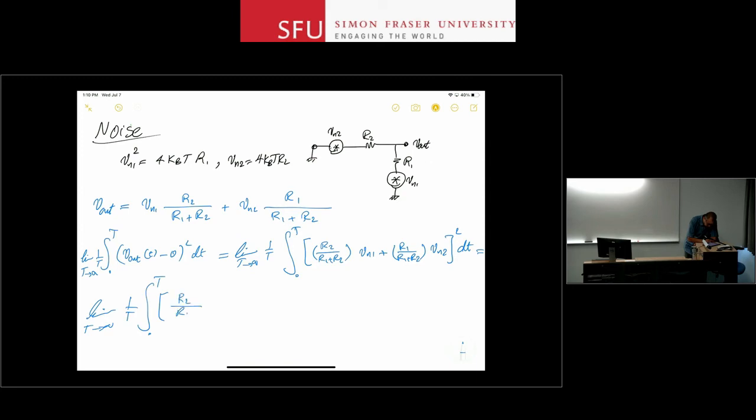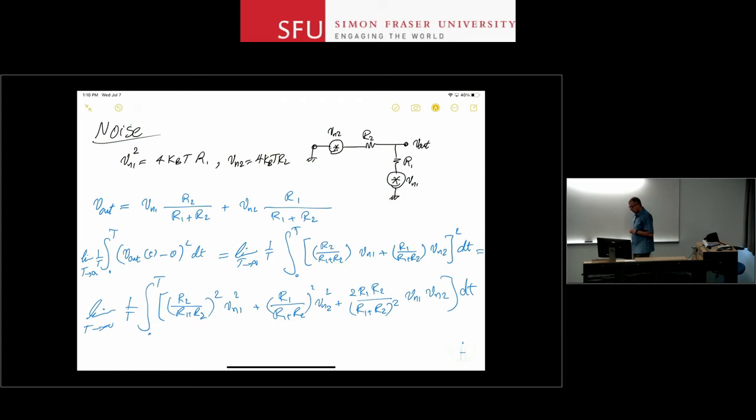So R2 over R1 plus R2 squared Vn1 squared plus R1 over R1 plus R2 squared Vn2 squared plus the product of the two, R1 R2 over R1 plus R2 squared times 2 Vn1 Vn2, the whole thing dt. Okay? So far so good, right?